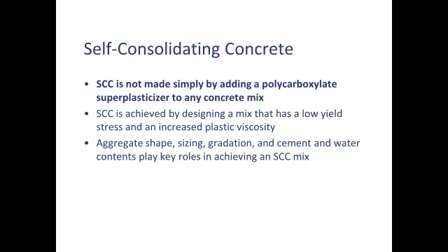And to make a true self-consolidating concrete, you really have to look at careful aggregate gradation, microfines, and cement-water balances. It's a fairly complex process, and it's very specific to your ingredients. So I could give somebody a recipe for SCC that I developed for my mix ingredients here in Raleigh, North Carolina. But if you happen to be in Sydney, Australia, your aggregates are different, your cements are different. That same exact recipe may not work. It's very, very carefully tuned to the aggregates.